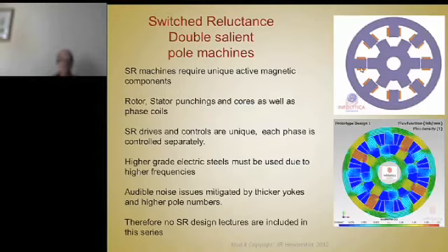Now, in this particular case, the one at the top, you have only 2 rotor poles that are attracted at a time. In the lower picture, you have 4 rotor poles attracted at a time. So the frequency of switching, or the commutation frequency, is different in the stator yoke, the stator teeth, the rotor teeth and the rotor yoke.